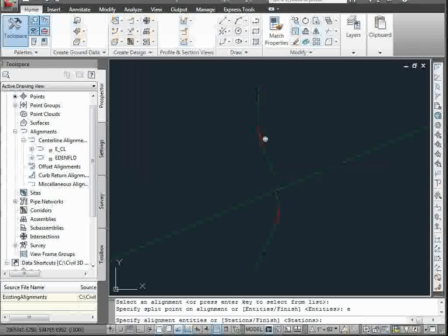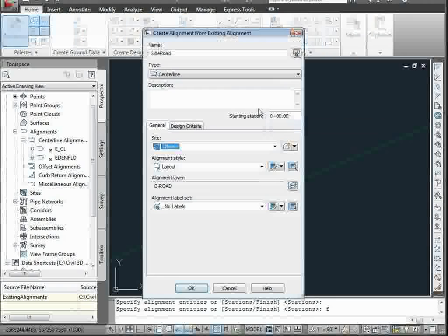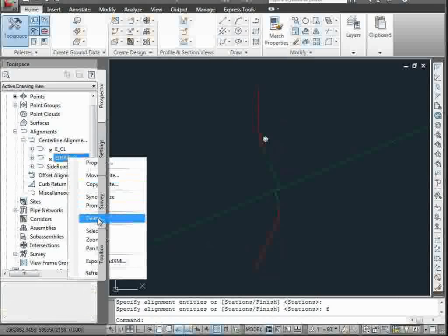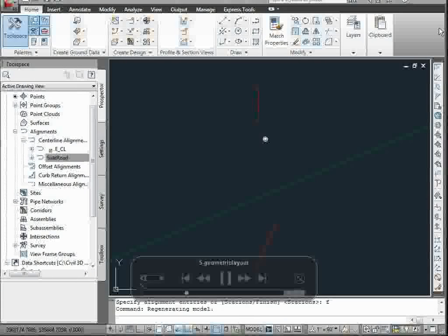So one of the things you have to do in civil engineering, obviously, is come in here and put in pure coordinate geometry. So what we're doing right here, we're going to take the tail ends of these roads and make a separate alignment out of it, okay? So I'm going to grab the bottom and the top, or in other words, the southerly part and the northerly part, make geometry that I can use out of it, and then I'm going to turn around and use straight up geometrics to compute how the geometry should fit together.